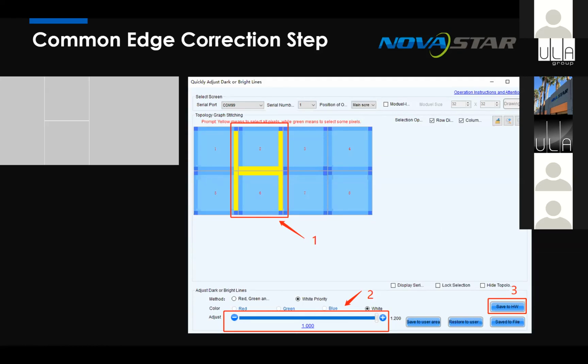One of the other things you need to be cautious of if you're running Windows is to make sure that you haven't got any desktop scaling turned on, because by default now on laptops Windows will change the scaling to be higher than 100% to make it look nice. You need to ensure that your desktop scaling is set to 100%, otherwise it's not going to line up properly. But once you've done those two things, this grey square should match the exact pixel spacing of your screen. And once you do that, you'll get this option here that shows the cabinet sizes on your screen.